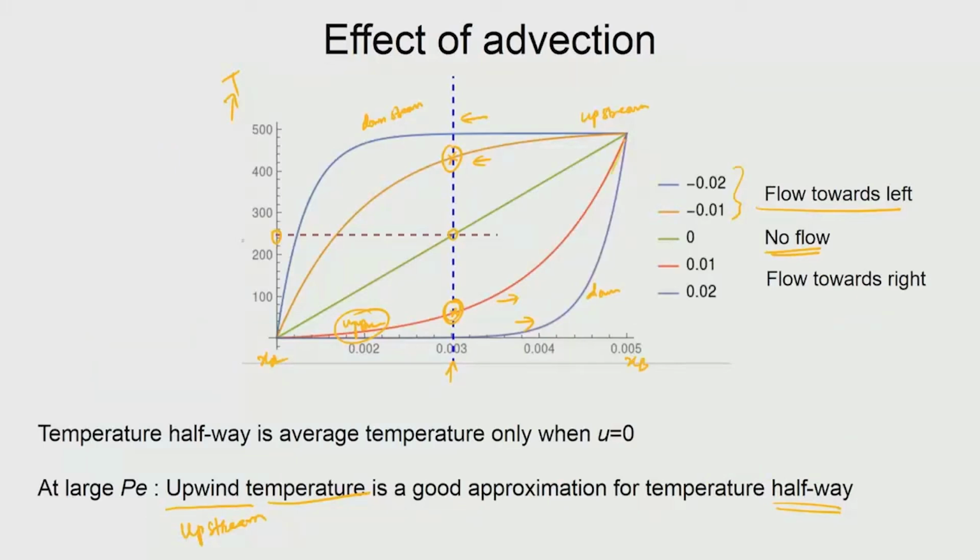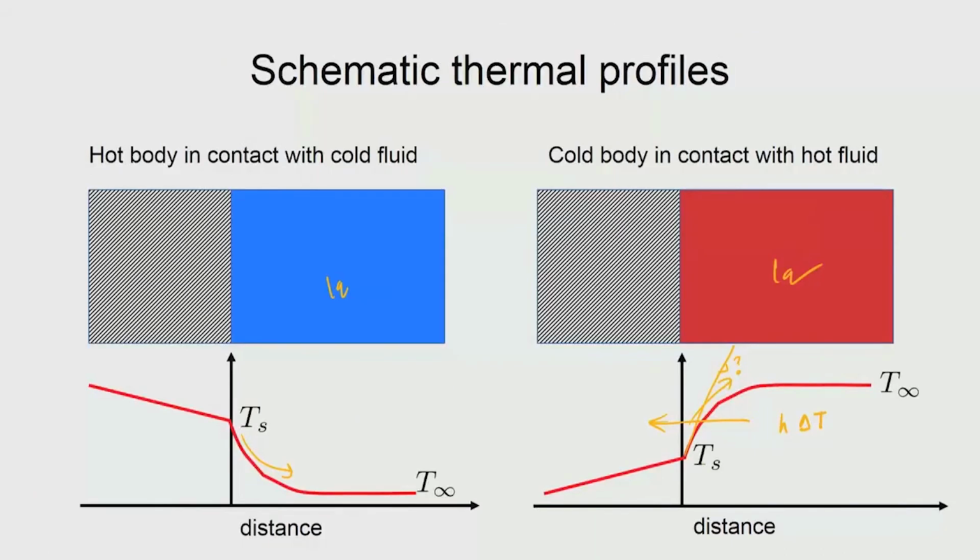The slope here, for example, is a function of the velocity magnitude, which we do not know in a general situation. So, naturally we cannot use the Fourier heat conduction equation here, we need something different. So, we use a dump factor, the heat transfer coefficient. This is the reason, and these exponential profiles were drawn earlier itself, but we now know the meaning of why we are drawing them that way.